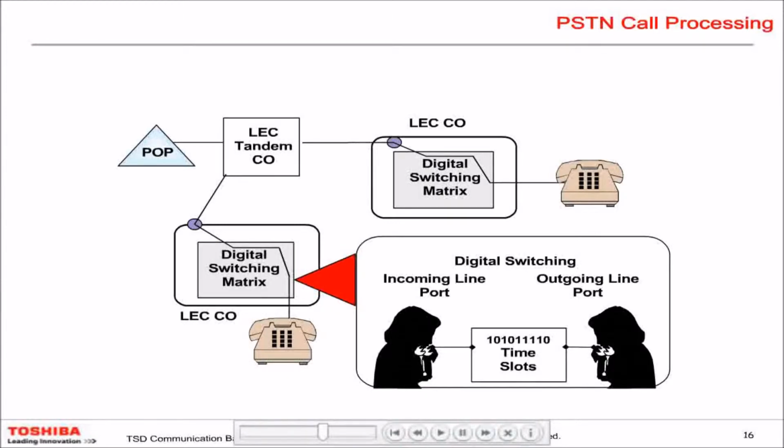It's a port-to-port connection established through the signaling to the called party, and the calling party gets ring back and then an answer signal. And then the conversation is assigned to a dedicated time slot through the length of the call, giving it exclusive use of that circuitry. When the call is completed, they get a disconnect signal and detection. Only when the conversation is ended does that time slot in the network circuitry become available for another call.